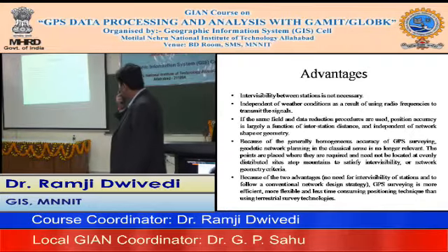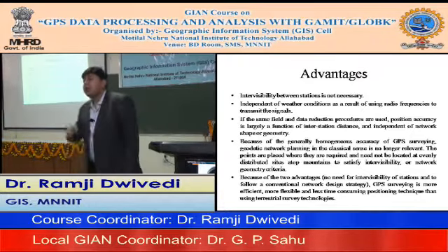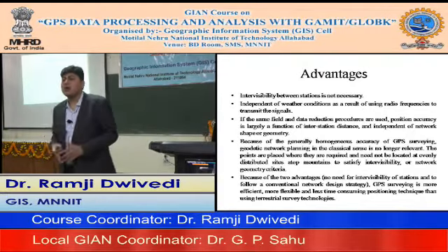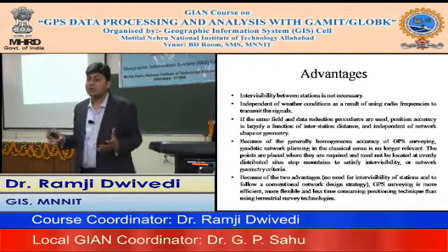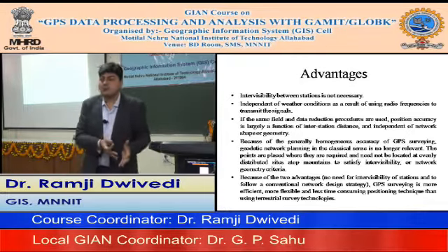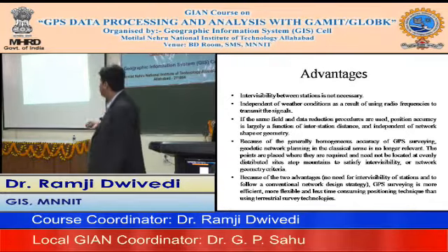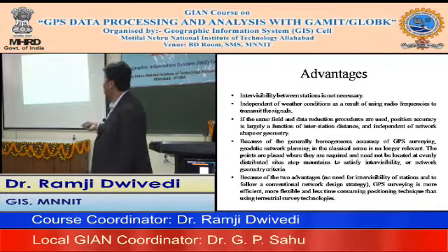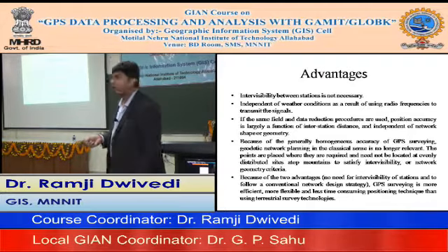Certain limitations are also there. In future you may have access to very precise receivers cheaply. A dual frequency geodetic receiver now costs more than $30,000 US, and in future you may have access to it at less than $2,000. But nowadays, if you want highly precise data, you have to choose high efficiency, and efficiency has a price. So it is costly if you go for dual frequency receivers. Handheld receivers are very cheap, now available for less than 35,000 Indian rupees.